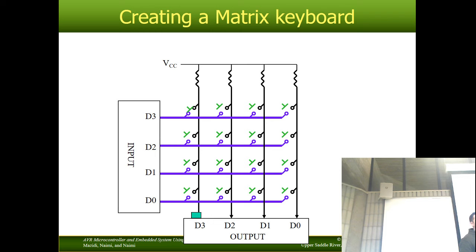So what actually is going to be happening is we're going to be doing it the reverse. We're going to be active low. I'm going to ground this terminal. So it'll be grounded. This is pulled up normally. So when I do this, it will actually connect me to ground. All right. If I were to press a button that wasn't grounded, say this button, I would see 5 volts here because it's pulled up.